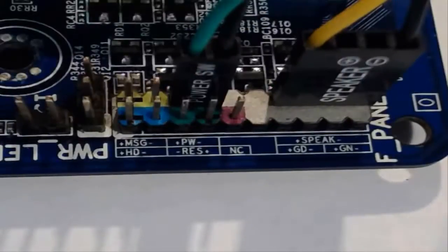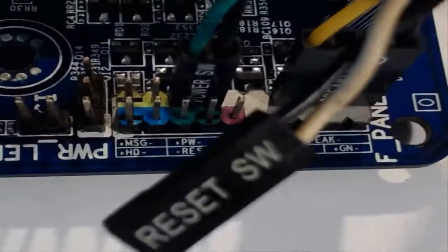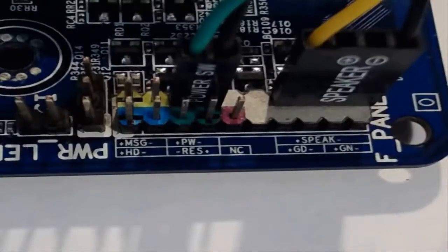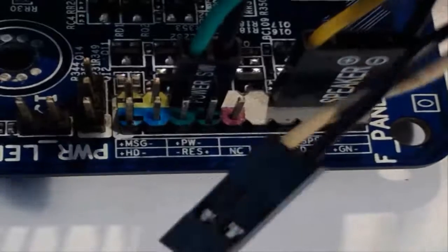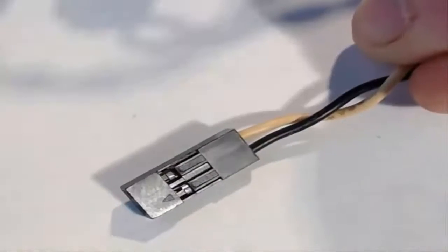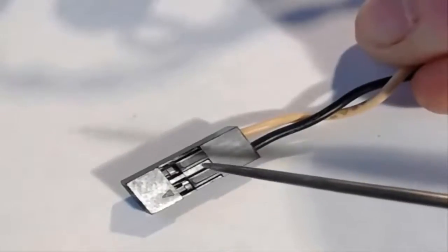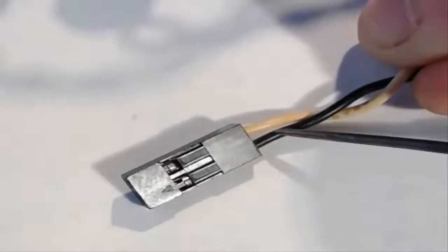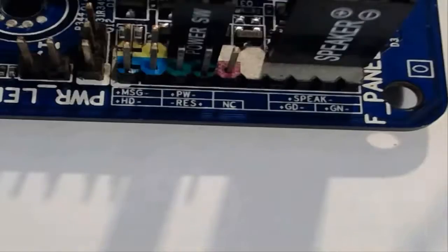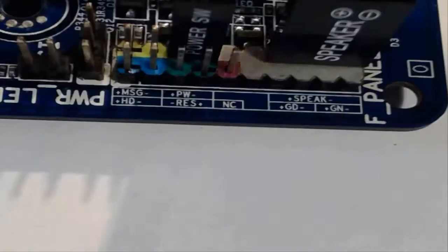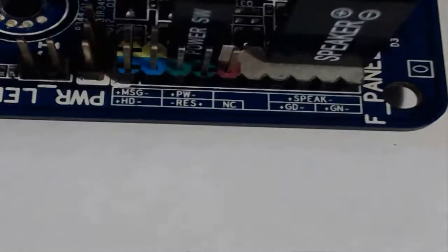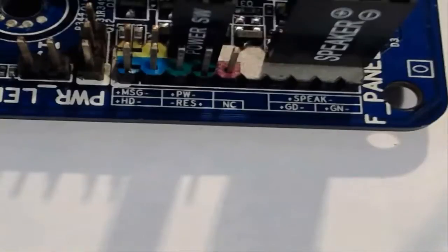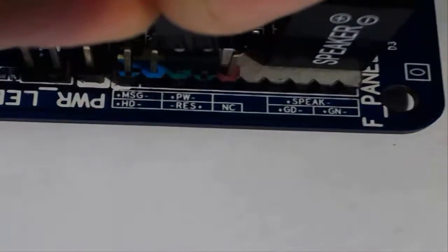And the next one then is the reset switch. The reset switch goes in front of the other one, and it's turned so there's no indicator on this one. We turn it around, we'll see a little arrow. See the little arrow again? There it is, and it's the black wire in this case, and it goes into the green one there, and the positive is on the right of that little green connector. So we just drop it down on top of it, like so.